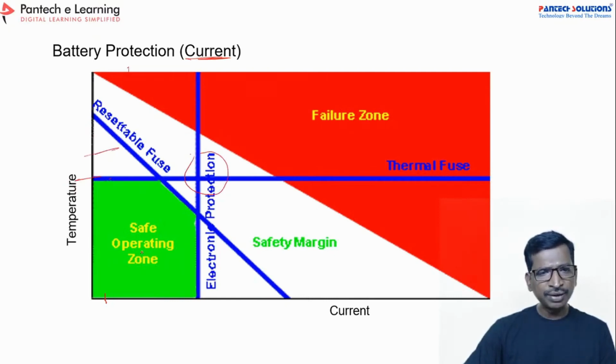Whenever the temperature rises, suppose you take 100 degrees Celsius, and at this point 10 ampere, 10 ampere with 100 degrees Celsius. In that case, the resettable fuse should take care, and the thermal fuse also should take care. And if any one of these fails, then definitely your battery is going to fail.